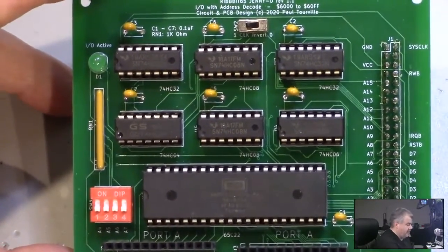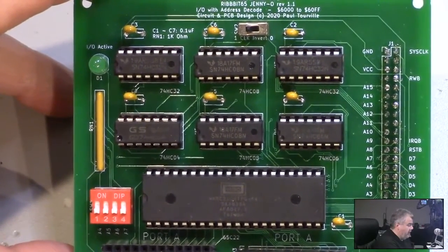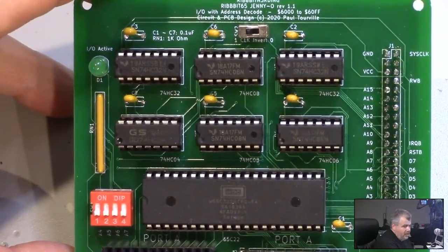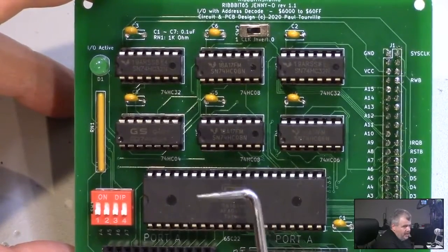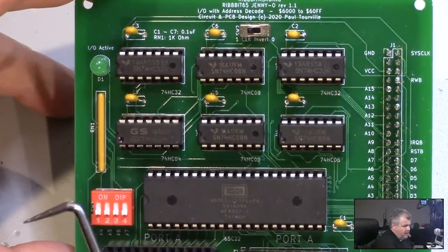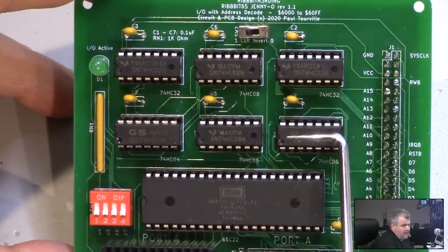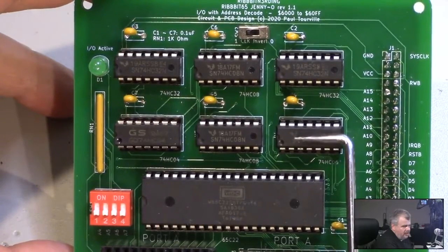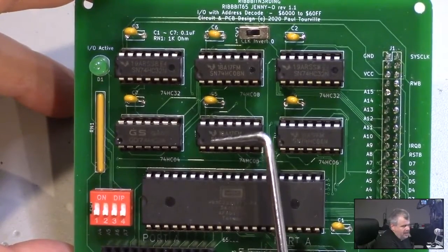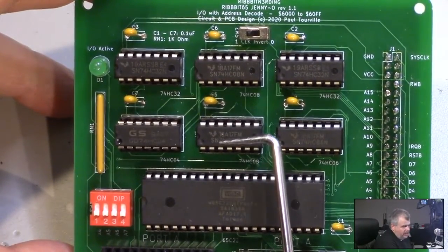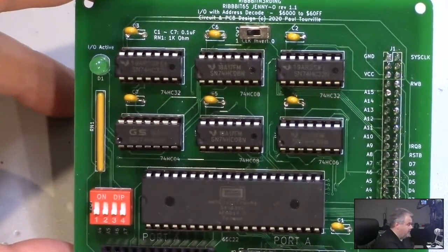Also, possibly of interest to the wider 6502 community is I have done a rework of this board to allow you, with dip switches, to set the desired MSB for the address that this is looking for. It adds a 7th logic IC because it requires 3 XOR chips instead of the 1 to accept the dip switch inputs.